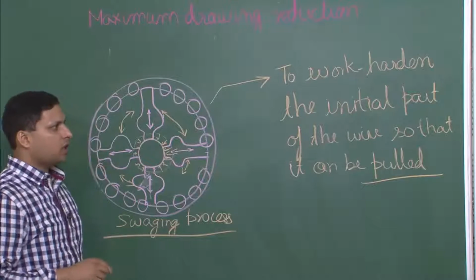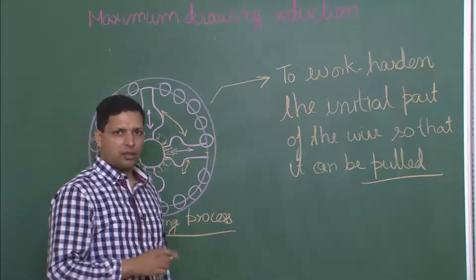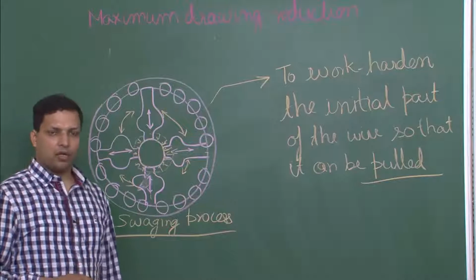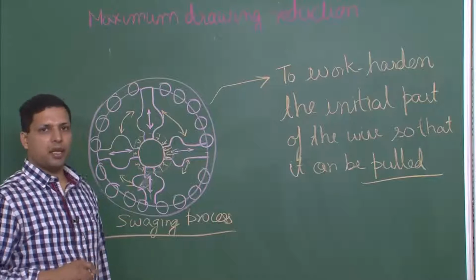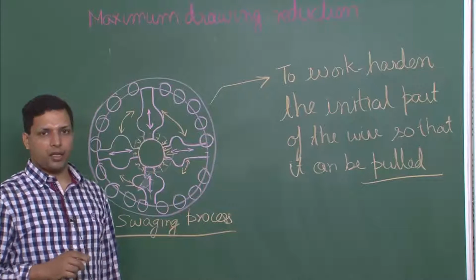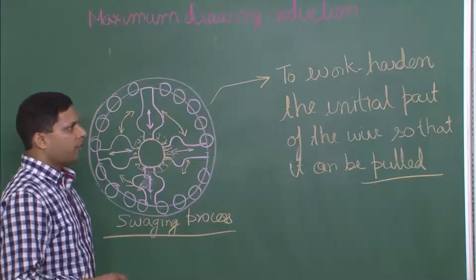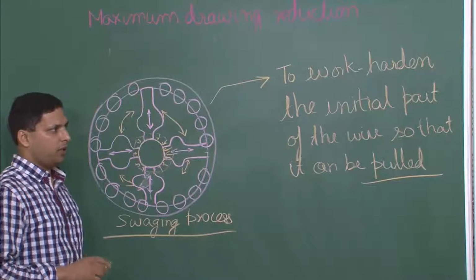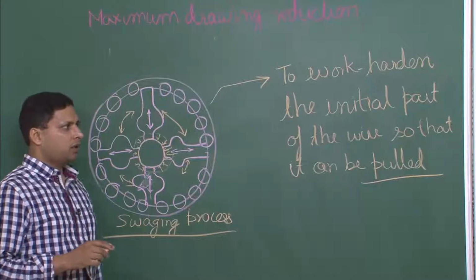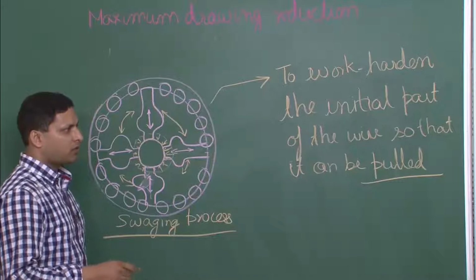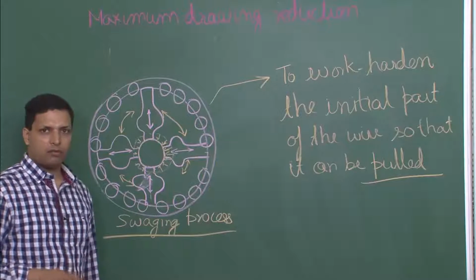And we also saw that under this condition of ideal stresses or ideal work, the drawing stress required to reduce the diameter is less than the stress you would need to get the same reduction in tension. So that covers most of the important or fundamental aspects of the uniform energy method or the lower bound method. You can extend this to any other kind of operation.